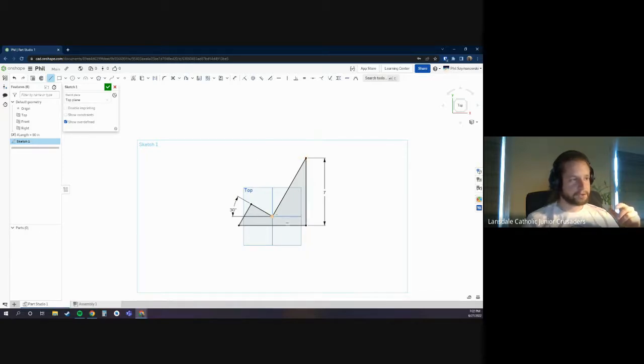And now if I mouse over another point, it's going to switch my preference for my constraint. It'll actually add both. So now I can be horizontal from that upper line and vertical from that lower one. If I come down here, it'll also imply the constraint as well. So if you do want something to be relative to some other point, you can make your life a little bit easier and not need to create as many constraints by creating these little implied constraint lines.